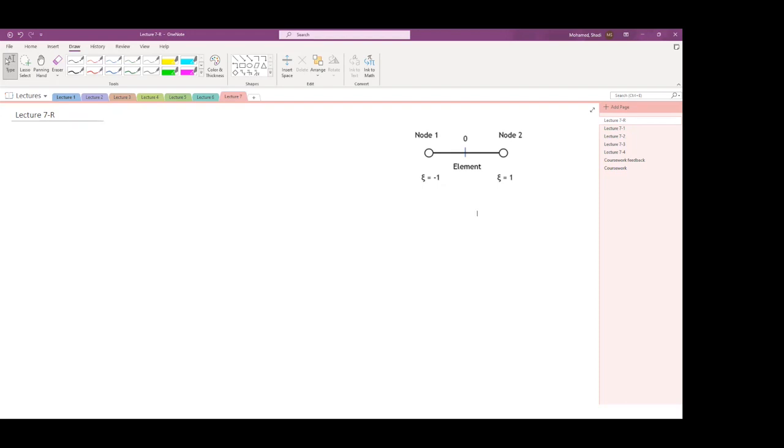All right, so as I said, last week we discussed the concept of local coordinates and global coordinates and how to relate elements in the local space to the global space. I'm just going to summarize what we did for the two-noded elements. We write the displacement in terms of the shape function, just like before. So u is N1, N2 multiplied by u1 and u2.